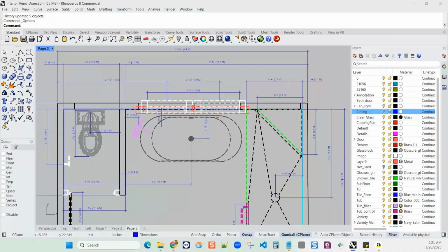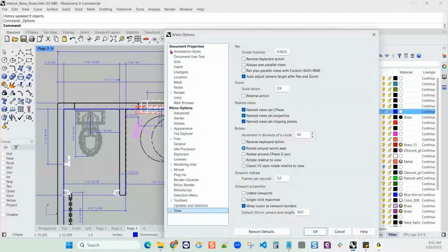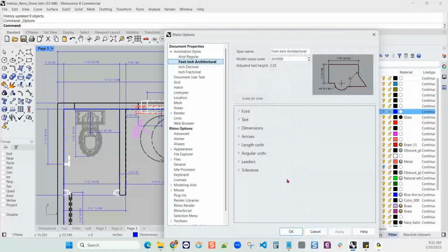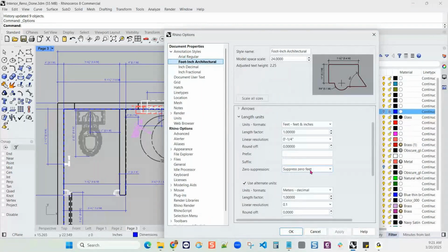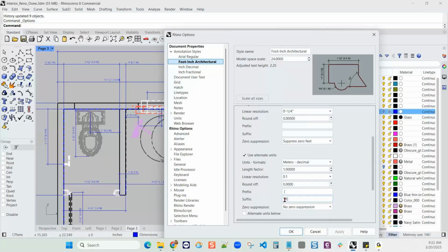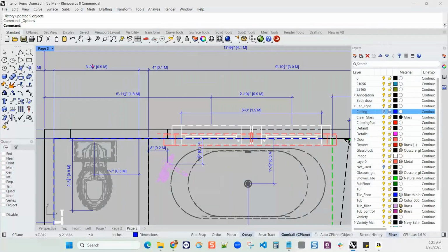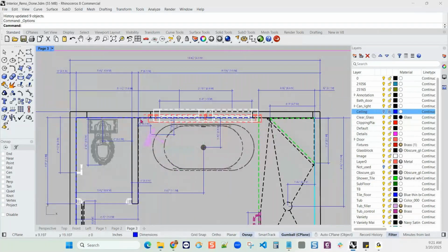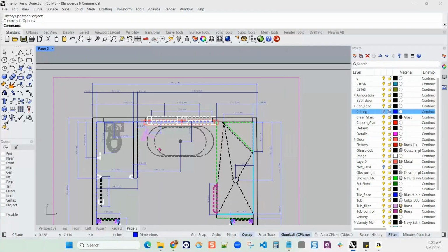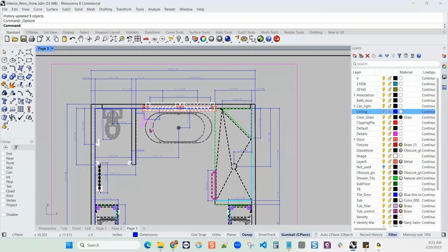So if I pick on the yellow gear up here, the annotation style itself supports multiple units, so I can have that alternate unit and put the M for meter descriptor in the dimension, so everyone here knows that we have dimensioned in both imperial and metric for this model. Okay, so that comes from the annotation style.